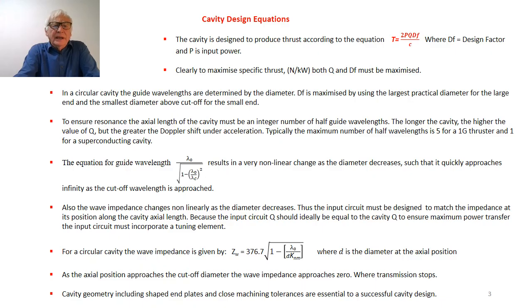And in a circular cavity, we determine the wavelength of the transmitted wave itself, which is designated lambda g.